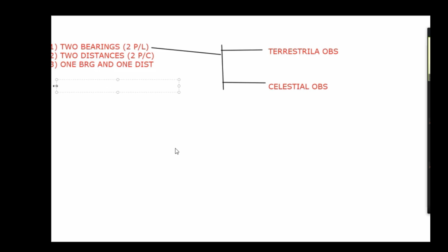In the morning, before the sun rises, we used to take it in your nautical twilight time, which is the best. In nautical twilight time, the sun has not risen, so it is still semi-darkness. You can see the star and see the horizon also. The horizon also should be clear. So this is the time you take the sight. But when the sun rises, the horizon is very clear, but the star you cannot see because of the bright sunlight. Now we cannot see anything, no star in the sky, but there are millions of stars in the sky. Similarly, the same thing happens in the evening when the sun sets.